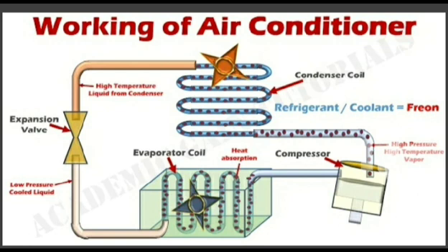The expansion valve depressurizes or lowers the pressure of the refrigerant and cools it down. It also controls the amount of refrigerant flow entering the evaporator. Now, the low-pressure cold liquid refrigerant enters the space where we want to produce cooling. That is, this cold liquid is now ready to absorb heat from the indoor environment and produce cooling. So, this low-pressure cold liquid refrigerant enters the evaporator coils.